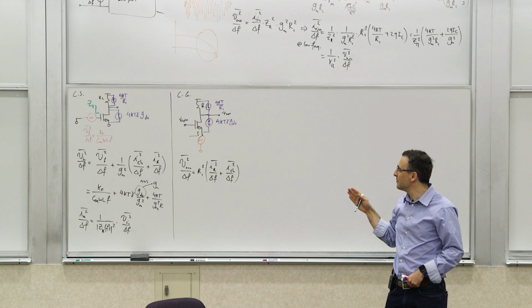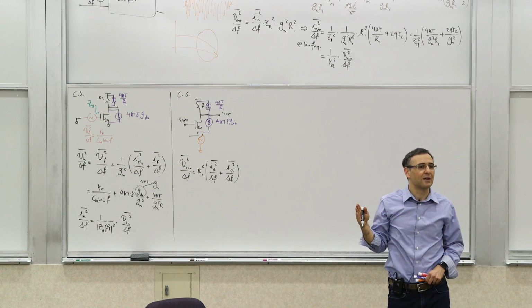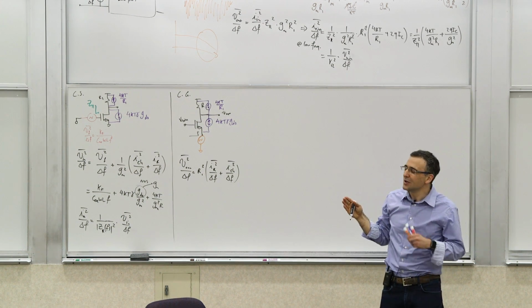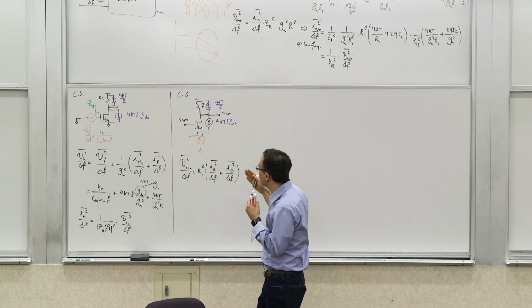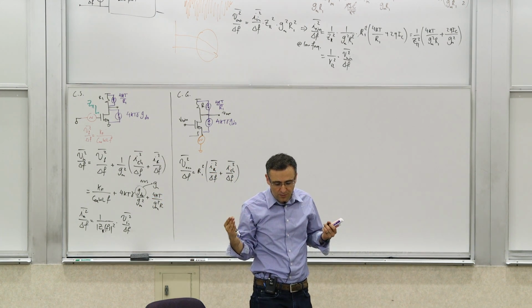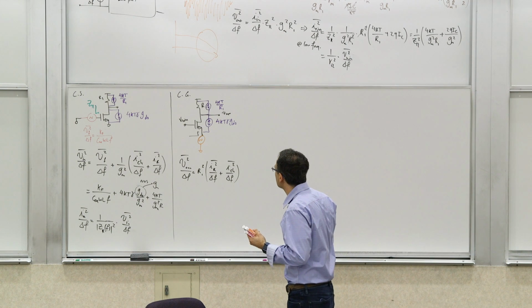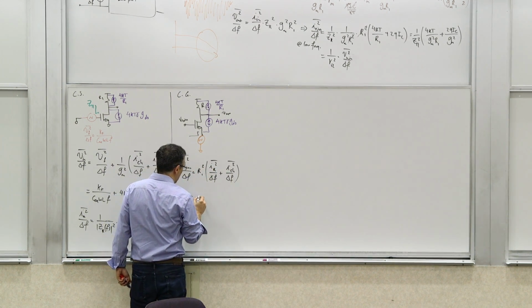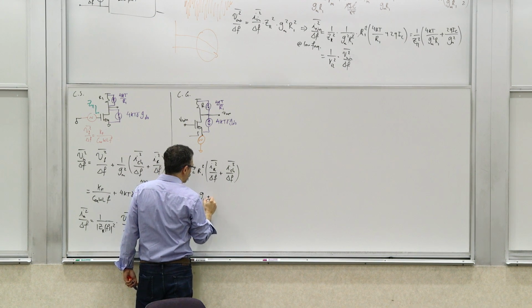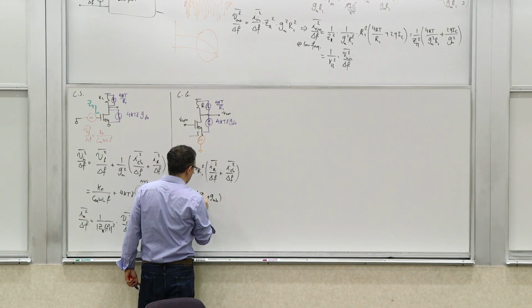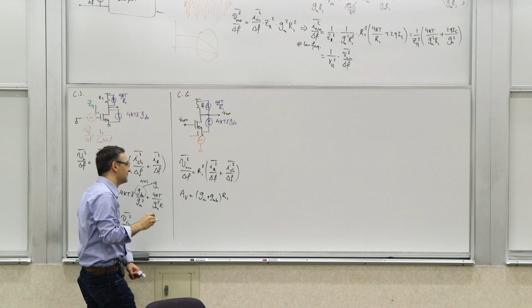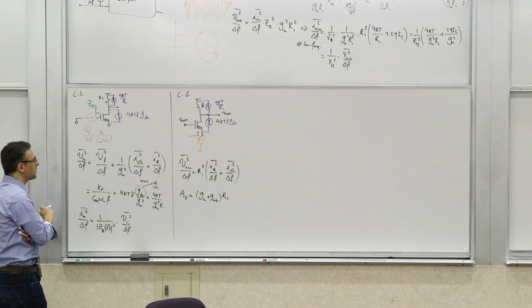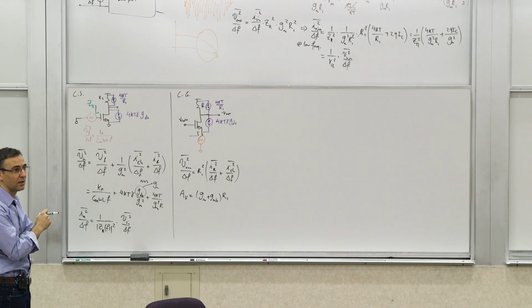If you have a MOSFET, for example, you have to think about the body effect. In the case of MOSFET, you saw that both of these things add together. So the gain, Av, is basically (gm plus gmb) R1 if you want to take that into account. If you want to ignore the body effect, it would be just gm R1. So that's the voltage gain.